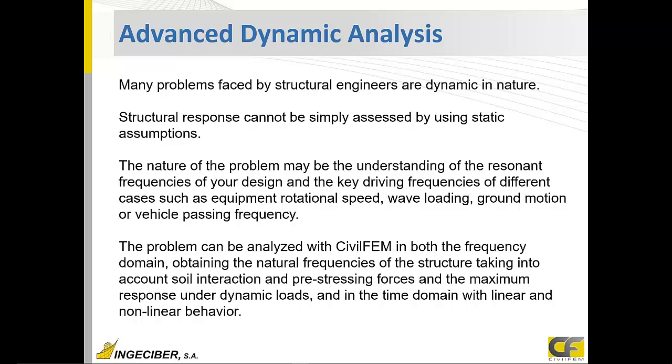With CivilFEM, we will see all the possibilities we have in the frequency domain, modal analysis and harmonic analysis, and also solving transient analysis. In transient analysis, we can add all sorts of nonlinearities: contact, material nonlinearities, large displacements. With these nonlinearities, we can have a much more detailed analysis.